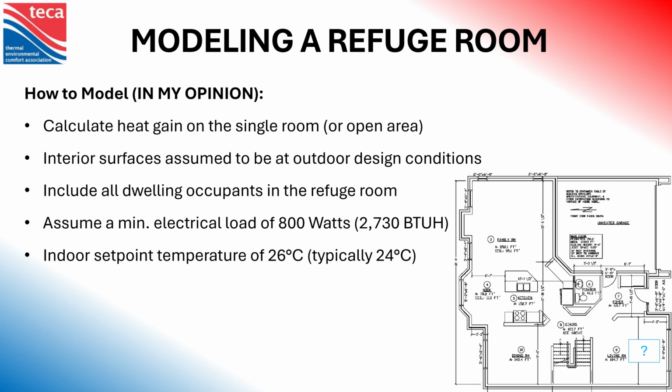So when we're looking at how to model a refuge room, this is my opinion, because as I mentioned, there is no set of standards. So these are the guidelines that I follow. I calculate the heat gain on a single room only. So what I do is I take that room and I model it as if it were its own independent structure.